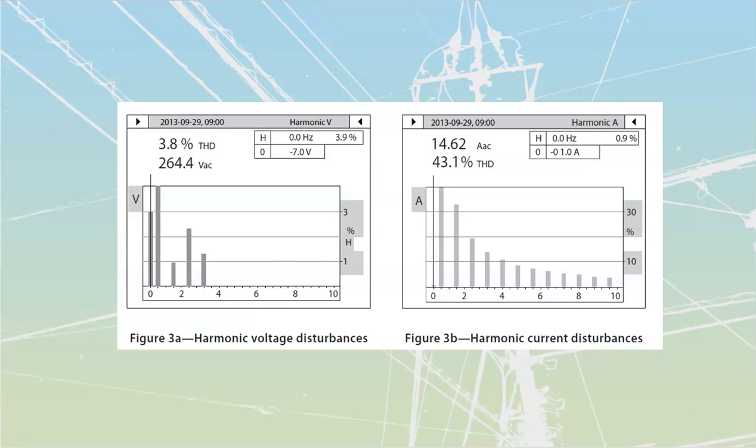Make sure your grounding and bonding are done correctly. Make sure that your bond size is significantly large enough that it can deliver fault current back to a neutral. And then make sure that your phase conductors, if you've got a lot of non-linear loads, are going to be larger.